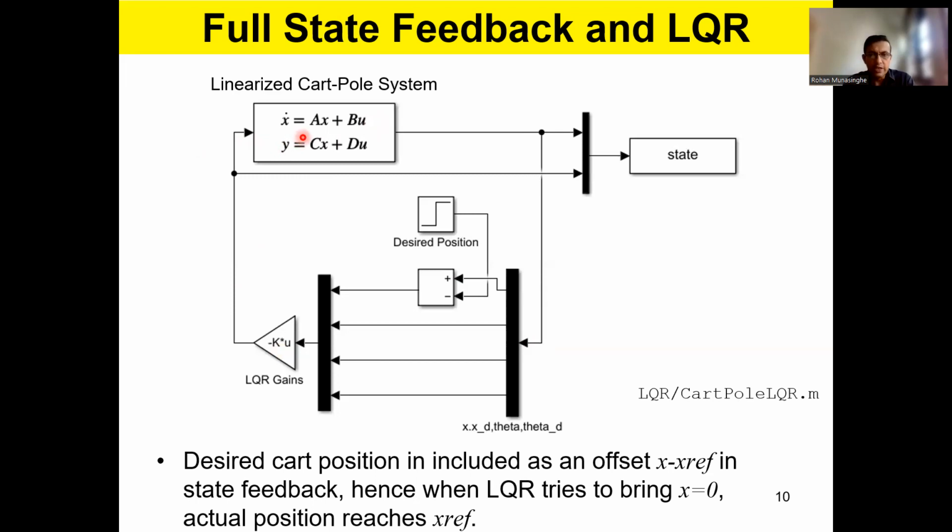Now this is what is called state feedback control. Only one problem remains. How do we calculate K? And for that also, if you refer to the notes, how we calculate the state feedback control, we call it pole placement. You can see how we do that. Pretty easy. The second control is the linear quadratic regulator. That is also a full state feedback type of control. Right? I'll explain that to you in a while when it comes to the slides.